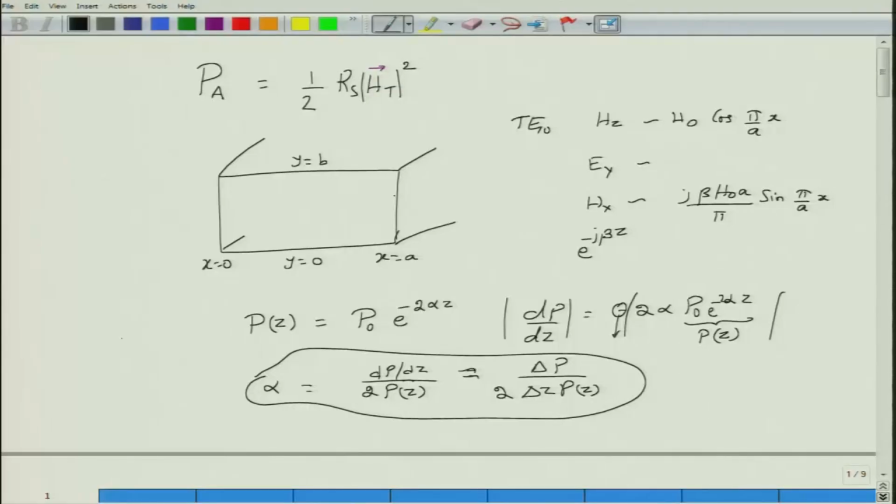The correct boundary condition would have been just a continuity boundary condition, because now this is not a perfect electric conductor. However, the procedure, if you were to try and implement that one, would involve applying boundary conditions on an imperfect conductor and then recalculating all of the fields, which is very tedious.